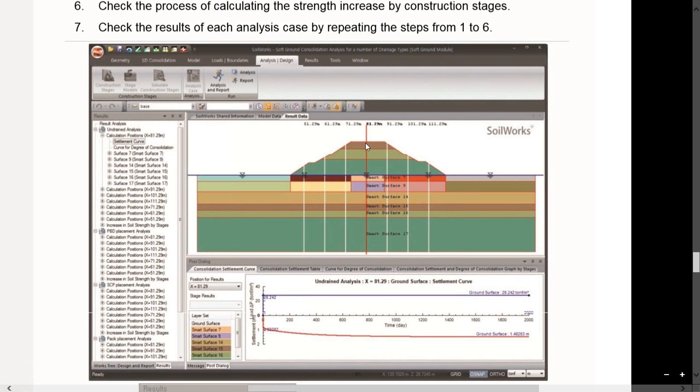I think this one has more secondary consolidation because there's a certain amount of loading on the embankment. I can't really remember, but go back and double check, and I'm sure you'll be able to see how the way this project was modeled allowed for a curve or a secondary settlement such as this.